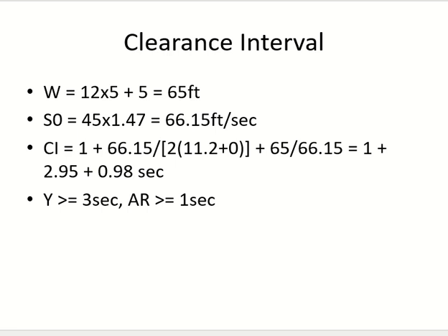Normally at the intersection there is no gradient. The road has a gradient, but at the intersection we keep it smooth, because the roads have different gradients, so it's much easier to keep the intersection straight and smooth. Anyways, this is the dimension of the road, and this is the speed again. So these two terms are yellow time. 1 plus this will give you yellow time. The last term will give you all red.